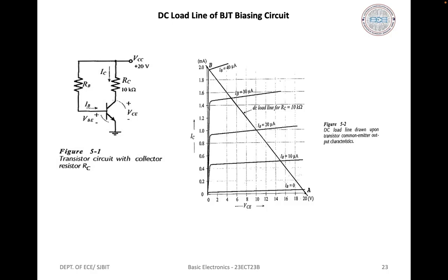The circuit that provides this state is known as a bias circuit. Ideally, the current and voltage levels in a bias circuit should remain absolutely constant. In practical circuits, these quantities are affected by the transistor current gain and by temperature changes. The best bias circuits have the greatest stability. They hold the currents and voltages substantially constant regardless of the hFE and variations in temperature.